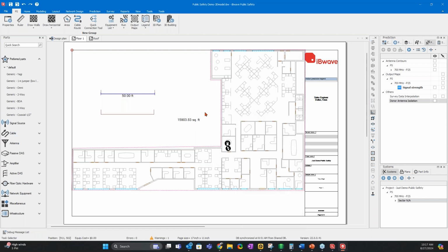Once we have done that, one more thing you learn in public safety is the critical area. Critical area basically means that for that area, I need 100% coverage. So what's our design criteria? 95% of the area. But the critical area means I need to cover it. Why? Well, when an emergency happens, if you think of a building, a fire happens, people say don't use the elevator, take the stairwells. Now you want to make sure the coverage is in the stairwell, where people are making calls or fire department people are using it. They should have a radio that works.